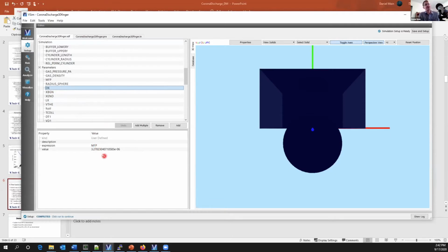This would be the largest you could make it. The reason I did that was because half an atmosphere is pretty dense, and this was pretty computationally intensive. So I just needed to reduce the number of grids. And because it's 3D, if I made dx half, then I would have 8 times the number of particles and cells.